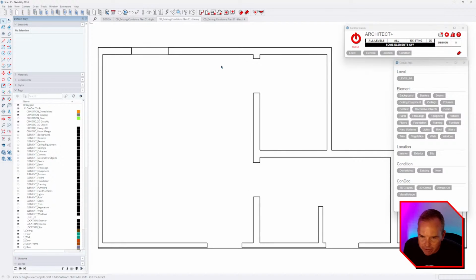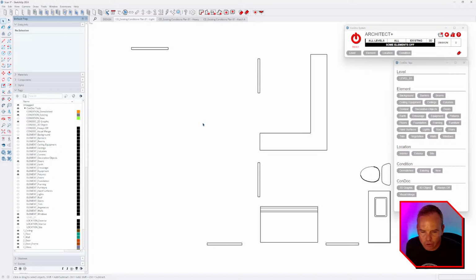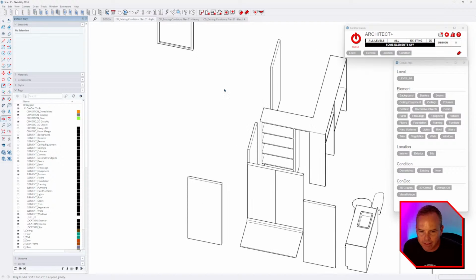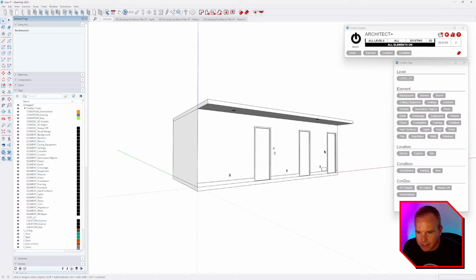We have a heavy line weight, so we can pull apart the walls and the floors and put them on a heavy scene. And then we can also pull apart our fixtures and our doors and windows and put those on a light line weight like that. All right, so I'll hit reset. Reset always gets you back to good.